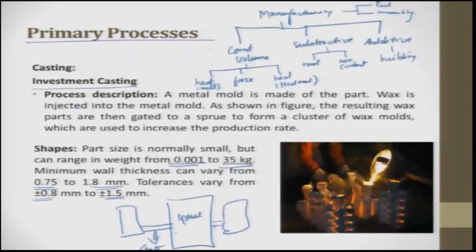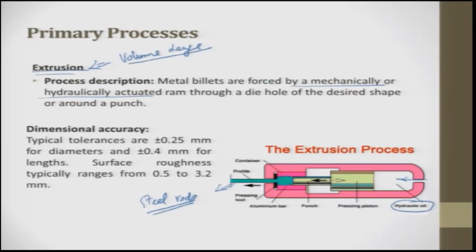In casting, you can have from one to maybe even 10 numbers of production, and a batch size can be 10 or even 100 parts. But when you talk about metal forming, it has to be large. We generally talk in terms of hundreds to thousands. Again, these numbers are not sacrosanct; depending upon the cost and the material, you keep changing with the processes.